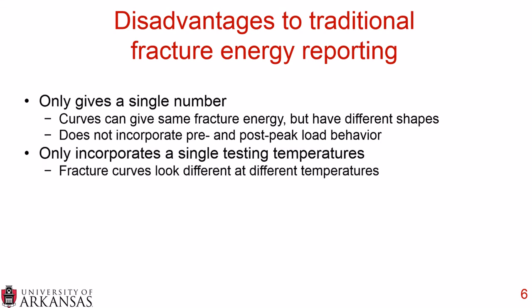In addition, it only incorporates a single testing temperature. And fracture curves look very different when they're at different temperatures. Because asphalt concrete is a viscoelastic material, it behaves very differently as both the temperature and the rate of loading changes. So how can we get some more information?